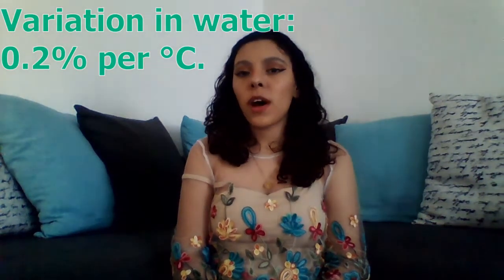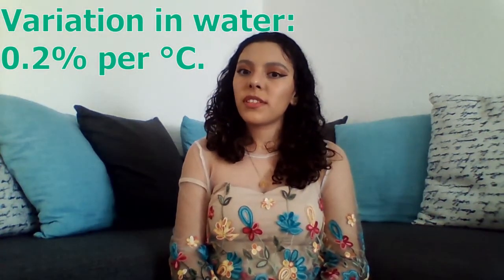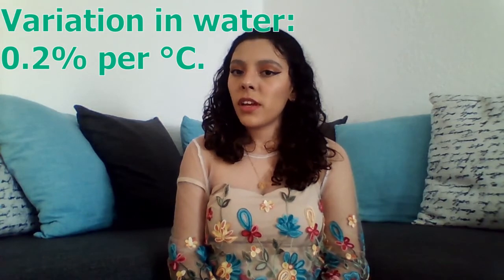Ultrasonic transducers are suitable for measuring the flow rate of most liquids, particularly those with suspended solids, unless the particles or air bubbles that the liquid may contain are of a size comparable to the length of the acoustic wave. They are also sensitive to changes in liquid density and therefore temperature, because these variables influence the speed of sound. For example, the speed of sound in water varies 0.2% per degree centigrade change in temperature.